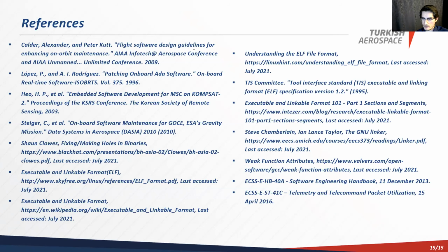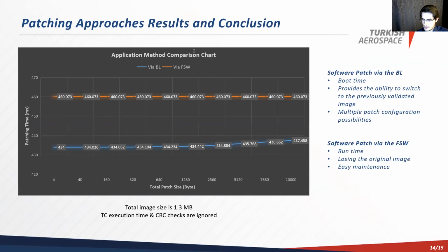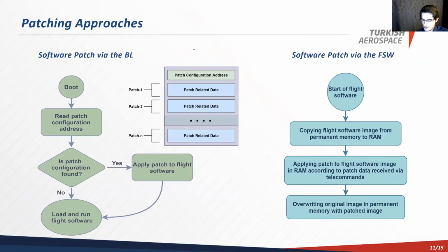And in the bootloader approach, you do not modify your image that is in the ROM memory. You basically transmit your patches to your RAM, and then those will be copied to this area that I mentioned over here. If you have anything, Jamal.